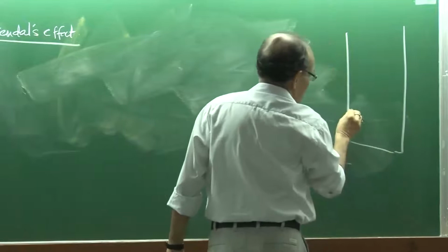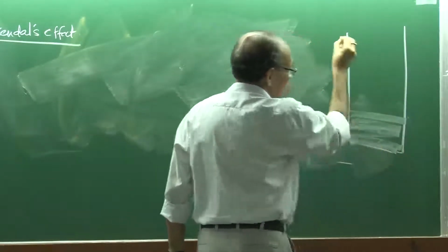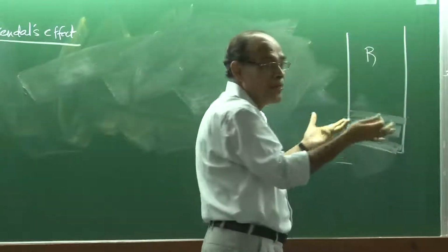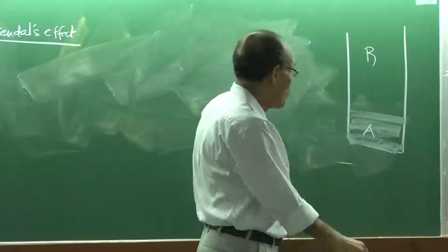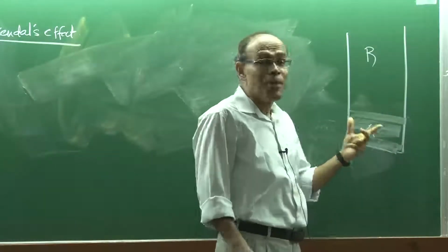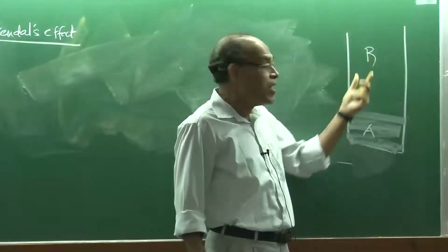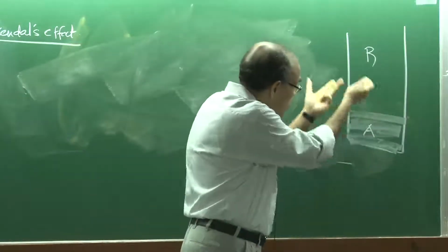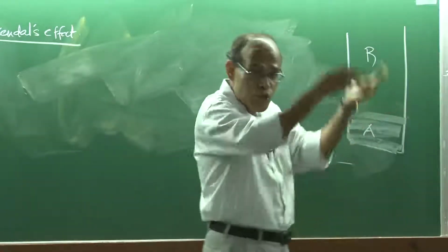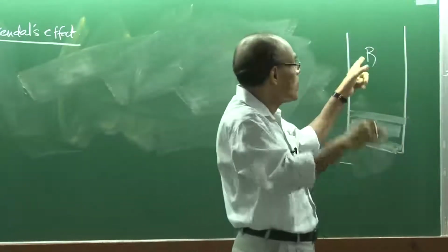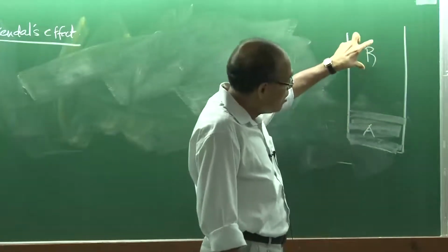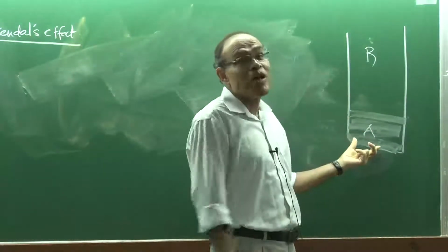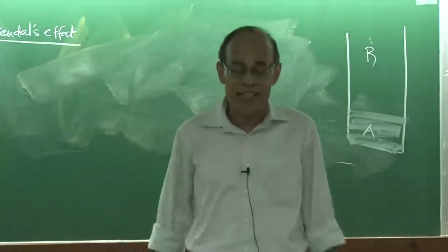told you about in the first lecture, I think, mixing of two gases, and I said that on top of the diffusion of A into B, there may be an overall movement of A also. There is a bulk velocity maybe superimposed on A depending on what the characteristics of A are relative to B. If A is lighter than B, then A will have a natural buoyancy tendency to go, and also the bulk motion of a large amount of A atoms can actually push the B atoms and may not allow us to find out the diffusion velocities or the diffusion flux of B explicitly unless we address this bulk motion component.